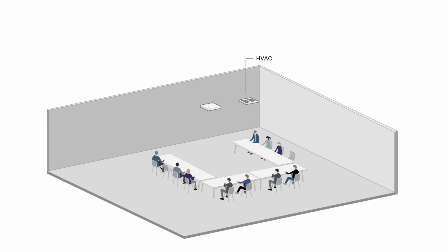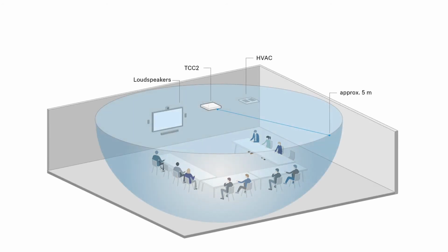The acoustic situation in a meeting room sometimes suffers from unwanted side noises, like air conditioning units, noisy doors, coffee machines, adjacent rooms. Also, loudspeaker systems for the far-end audio can be a source of interference for the microphone. In order to attenuate the noise of these unwanted sources, you can define exclusion zones in which the audio signals will be ignored by the beam tracking.